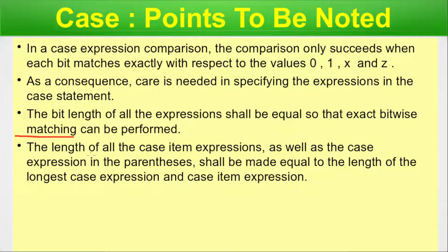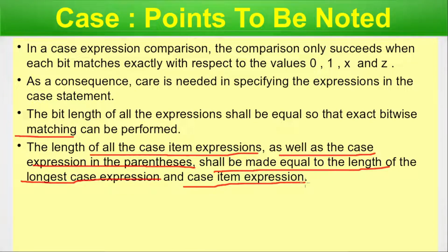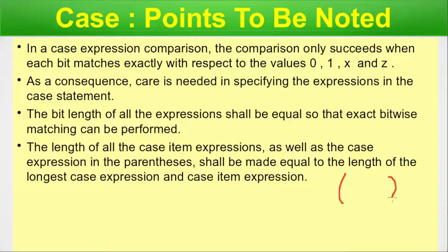Next, the length of all the case item expressions as well as the case expression in the parenthesis shall be made equal to the length of the longest case expression and case item expression. You have to be very careful about the length. That is what we are focusing on here. Whatever is in the case should be the superset of all the expressions.